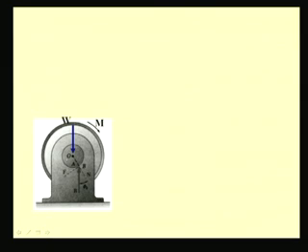So, that is what is represented in this picture. For a constant motion of this axle, the point of contact has shifted from, say, the lowest point A to the point B, and this is the frictional force, which is the kinetic frictional force existing between the axle and the journal. This is the normal reaction along the radial line, and the resultant of these two is R, which is vertical and equal in magnitude to that of W.